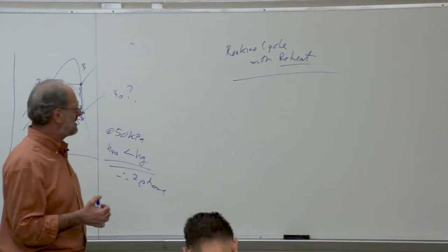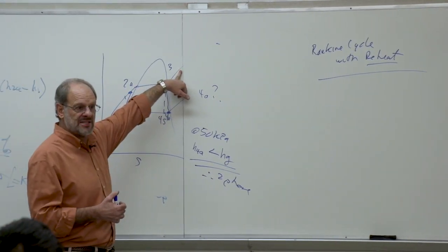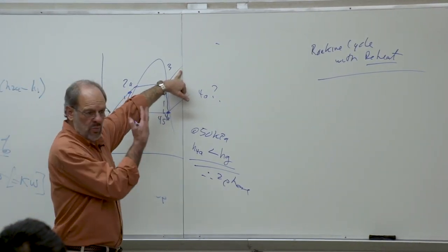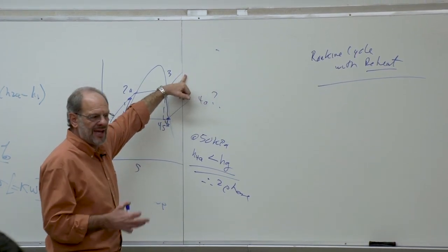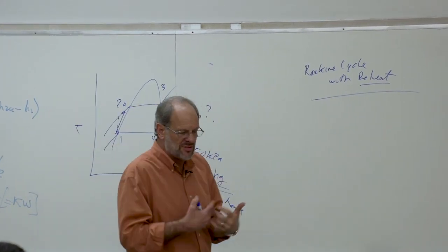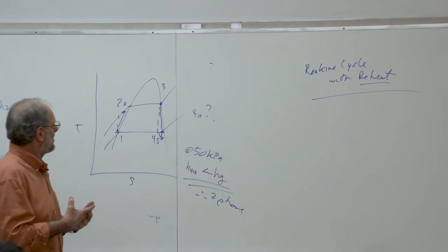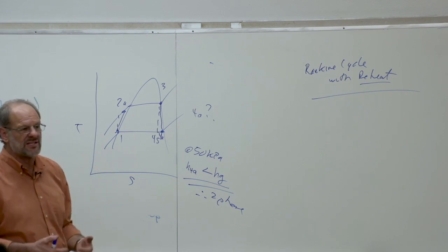If you add heat all at once, you end up with a really high exit temperature from, well, what would be the boiler in this case. Sometimes those temperatures are so high that you're not really able to find the appropriate materials for use in your steam turbine, and you have very serious, well, let's say materials concerns in that design.